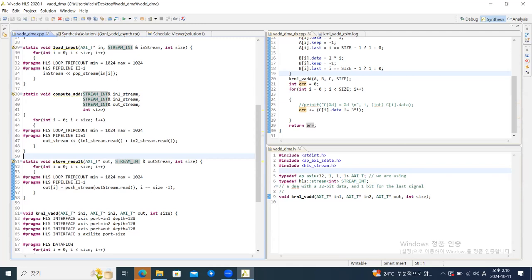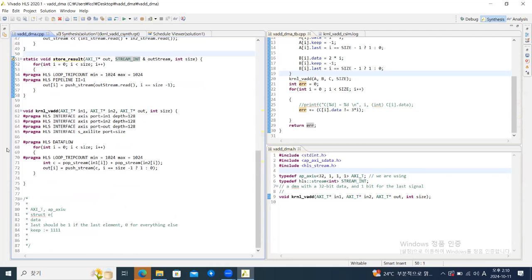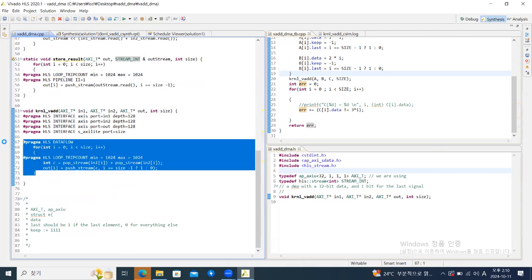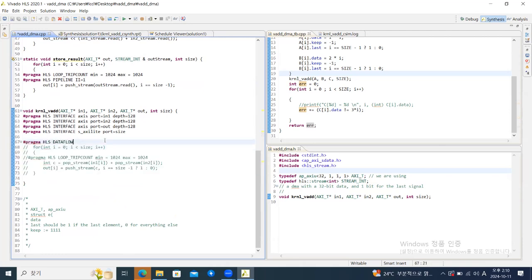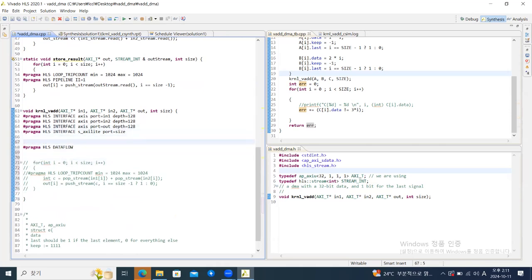And that's why, if you want to use the HLS stream, we need to modify the main function to have some FIFO stream. I don't know what to call it, but I'll just say that it should make a FIFO. Let's use this. Oh, I want to use the pragma dataflow. And we'll do something like static HLS stream int.